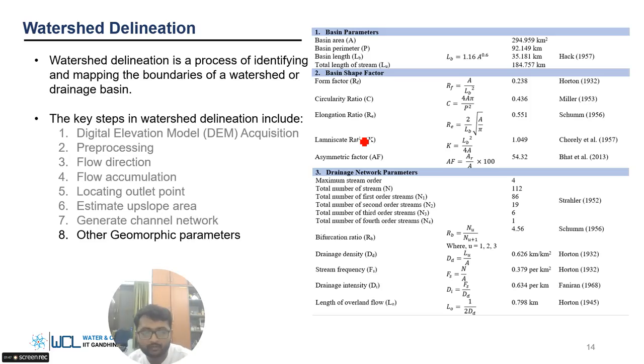And then there is the time of concentration and other hydrological parameters, which you can calculate. If you have LULC, then you can use the runoff coefficient and find out how much water it can generate on average, considering the runoff ratio for that particular part. If we have done deforestation or urbanization, how will it affect the runoff it is producing? Those are the answers we can give from this kind of analysis.